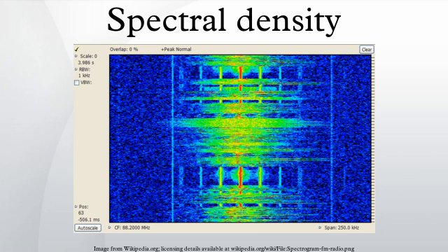The spectral edge frequency of a signal is an extension of the previous concept to any proportion instead of two equal parts. The spectral density is a function of frequency, not a function of time. However, the spectral density of small windows of a longer signal may be calculated and plotted versus time associated with the window. Such a graph is called a spectrogram. This is the basis of a number of spectral analysis techniques such as the short-time Fourier transform and wavelets.